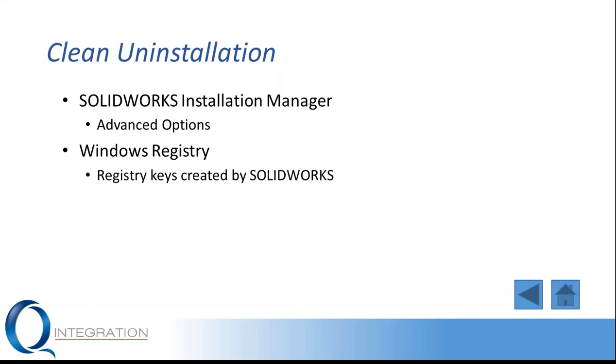We can also go through and do a manual removal through the Windows registry. So removing some of those registry keys that SolidWorks creates if we're not using the advanced option from the Installation Manager.